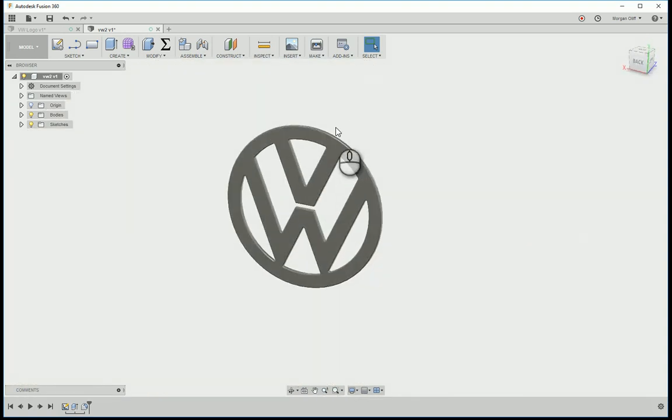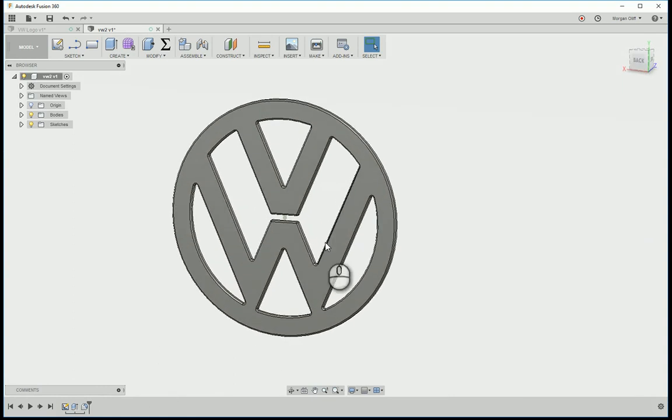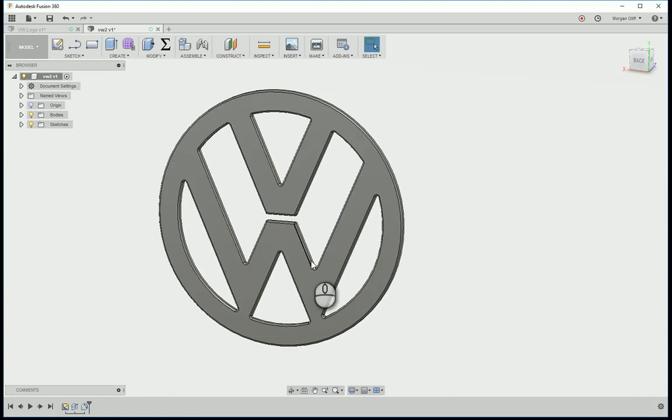Now, the one thing I didn't do is I didn't make that parametric to the outside. I may want to keep it that way, because if I make a 1-inch one, I'm still kind of only going to want to go down to a 16th inch cutter, like a 1.5 millimeter cutter. I don't really necessarily prefer to go down to one smaller than that.